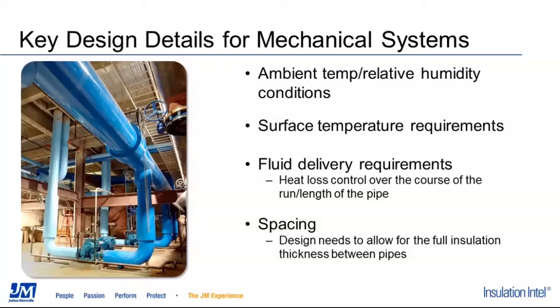And finally, spacing should be evaluated. When designing a system, allow for sufficient insulation thickness, and also let's account for the work that needs to be done by the contractors when working and installing insulation. And that will be insulation as well as jacketing.